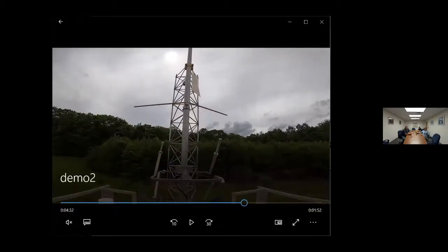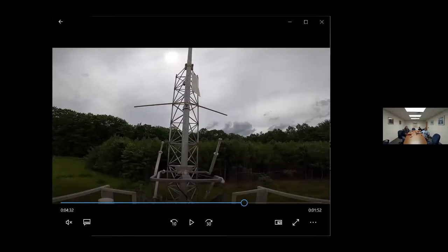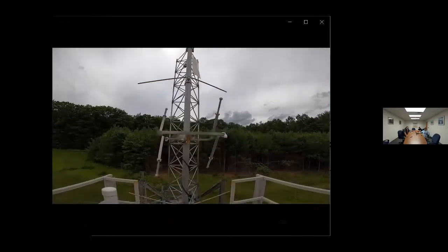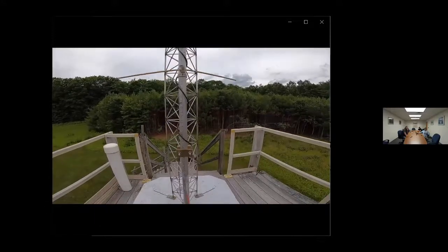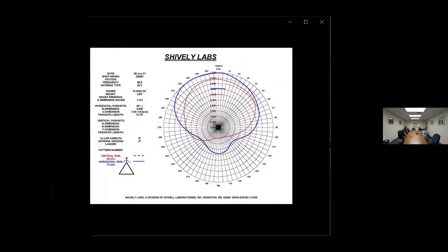So the design of the SLB and some other antennas like the 6815 are different from our ring and stub design. So they need a different type of parasitic. That type is essentially a horizontal para that's been bent to a certain amount of degrees. The placement is normally a quarter wave above and below the bay. I say typically and normally in this case because parasitics can take on a ton of different configurations, especially with the more crazy DAs and the more desperate I get with the study. I do normally around 20 pattern spins for a normal one, but I've done 100 or more in a few.